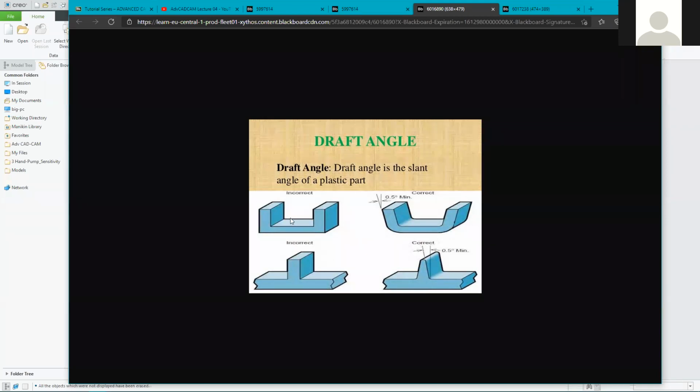Whereas if you do a redesign on this sort of mold setup and add, let's say, a half a degree angle to the faces, that would be a minimum value. The value for injection molded parts is probably nearer 3 degrees, let's say. Then you can see that if you were to pour some molten material in here and it was to solidify, it would be significantly easier to remove that molten material.